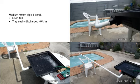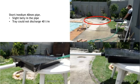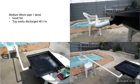Now, this is the same length of 40 mil pipe with a 90-degree bend, but it's just got a fall, and it's easily discharging 40 liters a minute, where in the slide beforehand, with a straight piece of pipe out, you can see it struggled. It in fact overflowed. So there's a massive difference in flow between pipes with a fall and pipes without a fall, and that's the crux of the matter that I'm getting to.